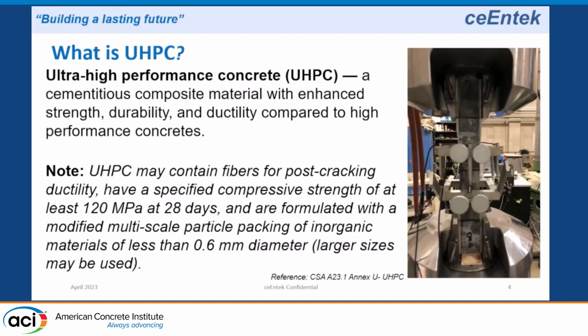So when you put concrete in tension, you have a brittle failure. It cracks, you have a rupture, and you have a failure. So you put rebar into that. In UHPC, we put microfibers in the matrix. The microfibers are actually stronger than the matrix.